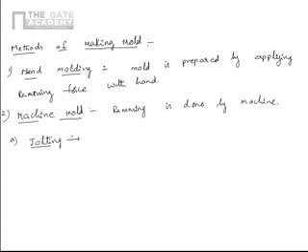In jolting, the sand-filled mold is raised up to a certain height and dropped onto the ground, then the ramming action takes place. By using guideways we drop the sand-filled mold. The potential energy possessed by the mold after lifting to a certain height is converted into ramming force as it hits the ground. From the ground there is an equal and opposite force, and then the ramming action takes place.